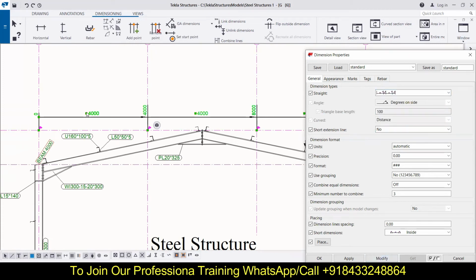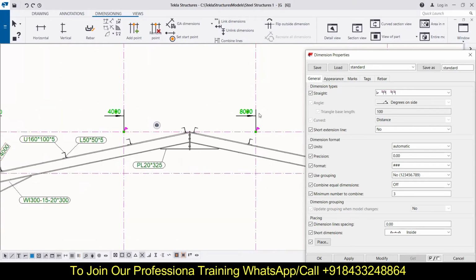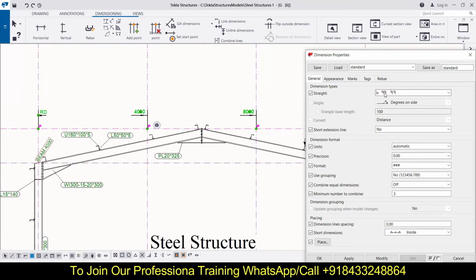So if you go with this format, then it will show you the distances between the two grid lines, as well as you can also show the final distance. Like from here to here it is 0 to 4000, from 0 to here it is 8000, and the distance between these two grid lines is 4000. Okay, so like this you can simply mention the distances, and you can see there are different methods of representing it also. Like you can go with the RD, then at this level it is 4000, then at this level it is 8000. So like this you can have the different types of representations also. Okay, so let's go with the next one.